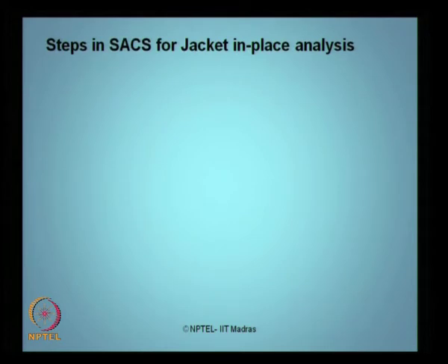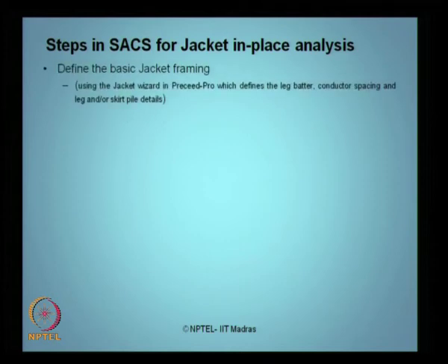So, let us take up the software SACS, which is useful for doing in place analysis of jacket structures. You have to first define the basic jacket framing, which will talk about the layout in terms of its elevation and plan for the member sizing available, and this can be done using the jacket wizard in Precede Pro in the menu, which defines the leg batter. Batter is nothing but the slope of the leg, because in jackets you will see that the leg is not vertical.